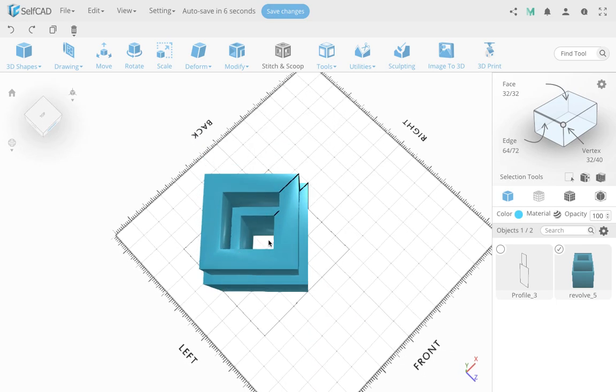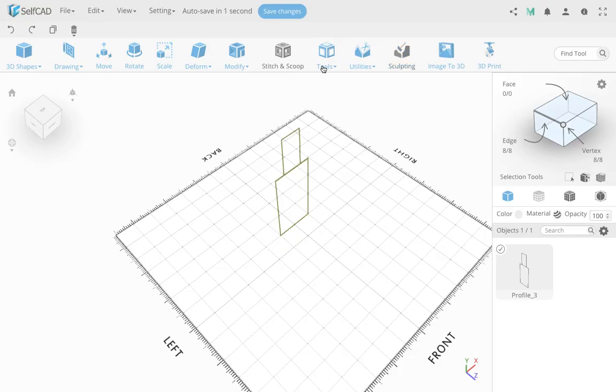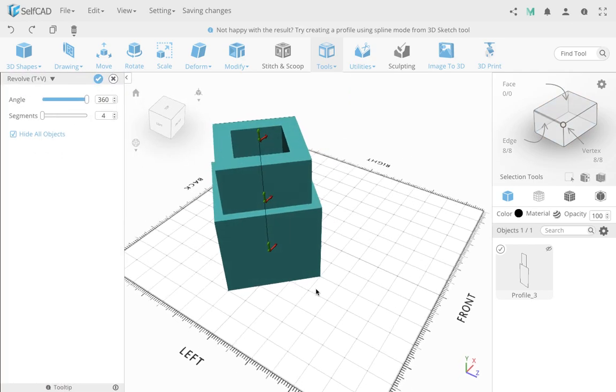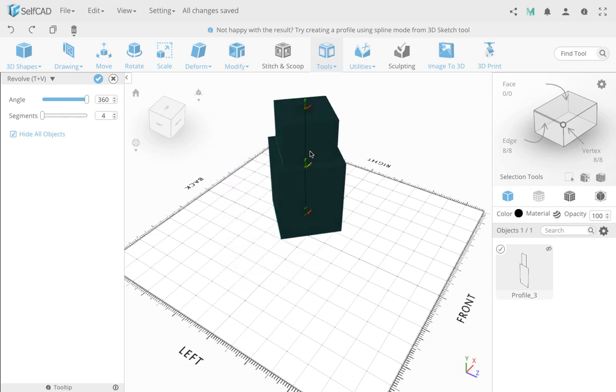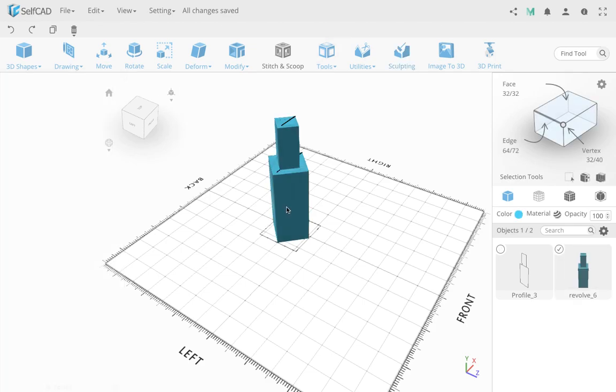But I want to have it closed now, and I want to show how it could be closed. So I'm going to undo this last step, and I'm going to go to Revolve again, but this time I'm going to use these tools over here, and these tools basically allow me to squish them together. You can see I'm moving it one way, and then once it comes to the zero point where the space is all the way collapsed, it will start going in the other direction. So I want this before it starts going in the other direction, something like this, and I'll finalize it.